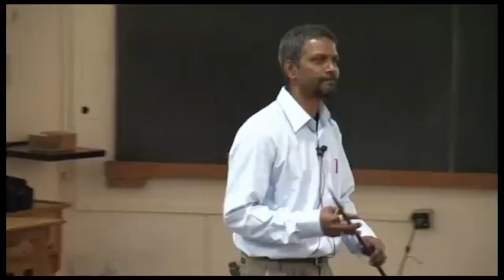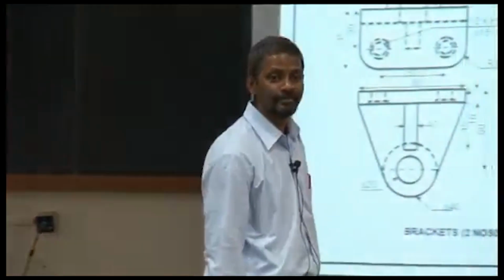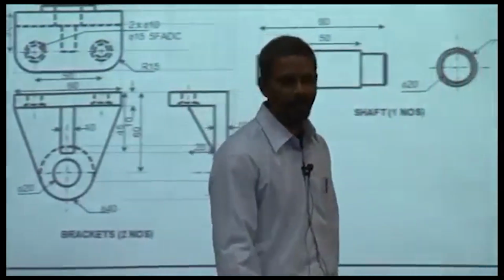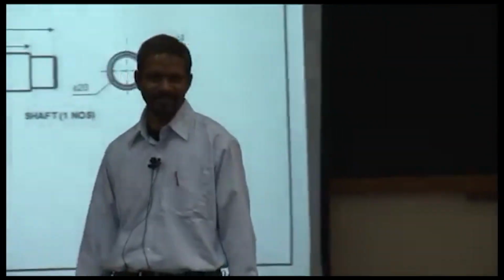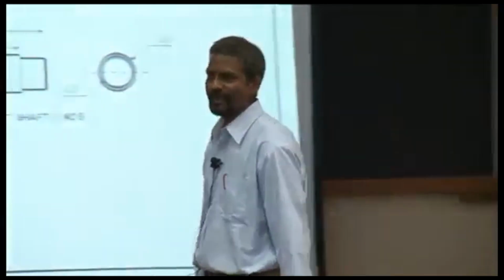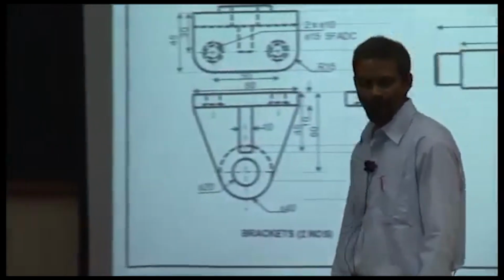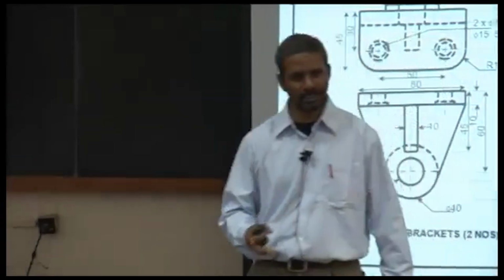Why only front? Why not top? Why not profile? Priority, FTP. Okay, so front view is the topmost priority view, then comes the top view, then comes the profile view. So you would want to show as much detail as possible with as much clarity as possible in the front view. And then comes the top view, and then comes the profile view.